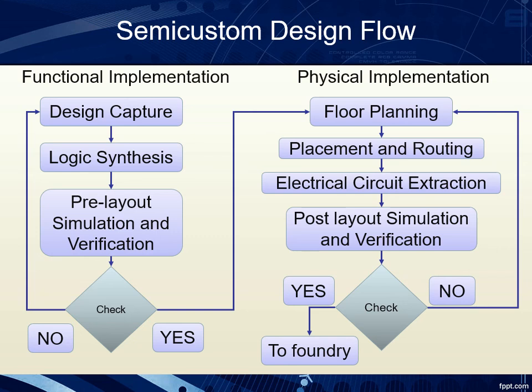From this layout, the masks will be generated and the integrated circuits will be fabricated. But if upon simulation and verification errors arise, we need to go back and repeat the physical implementation phase again until there are no errors that appear. So this is the design flow for the cell-based semi-custom design.